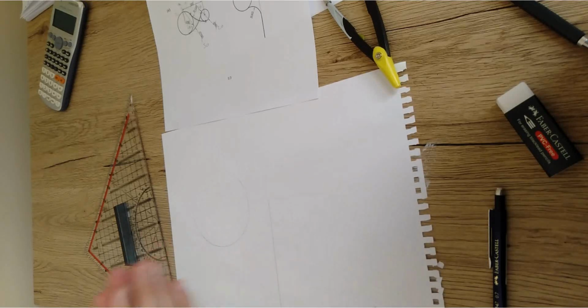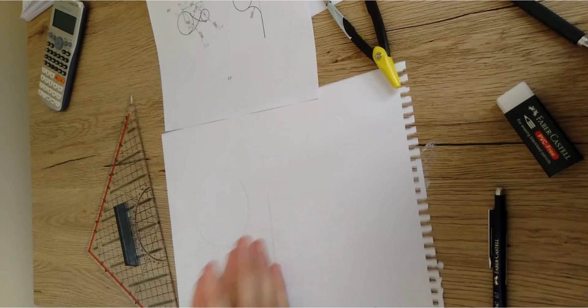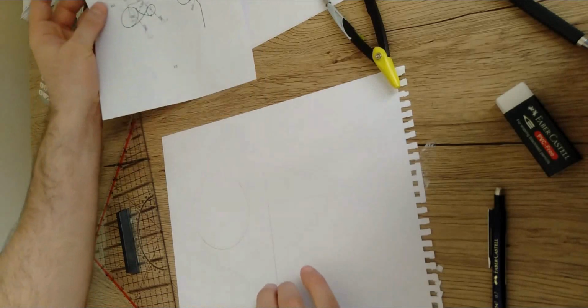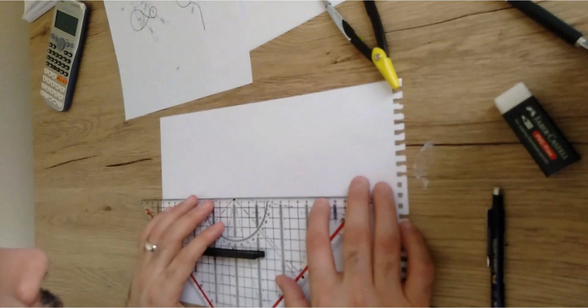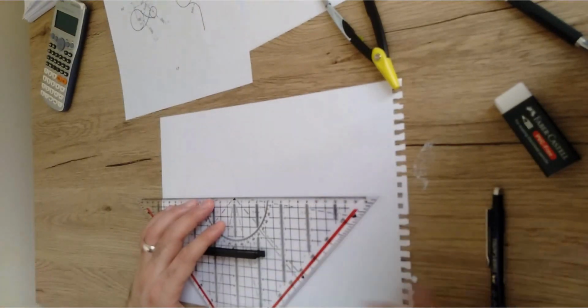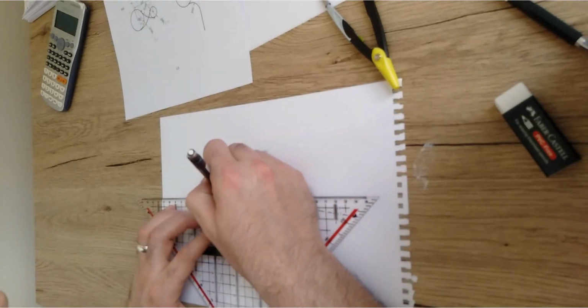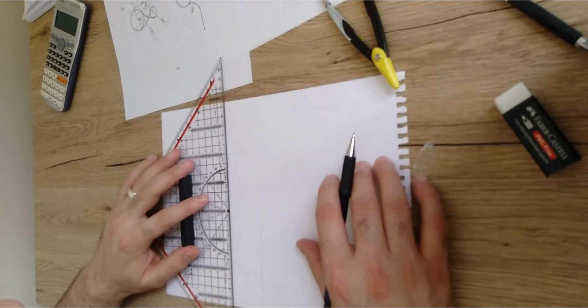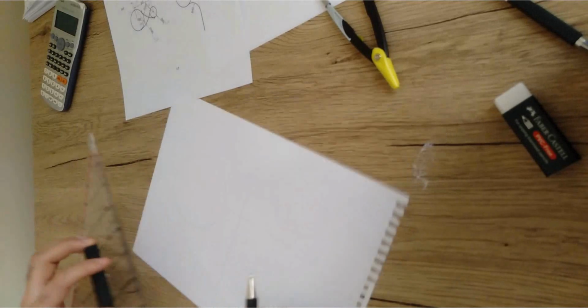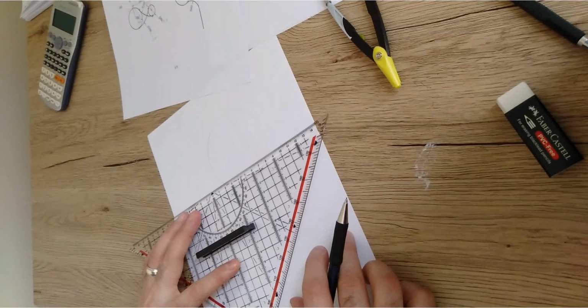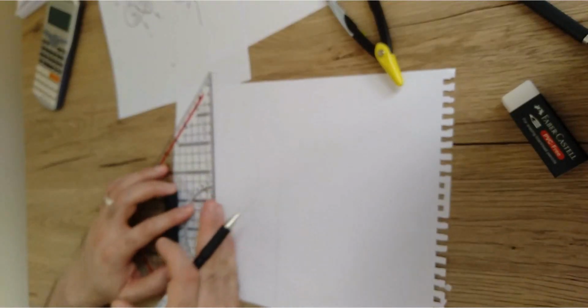For the line, I have to draw a line that is exactly parallel to this line, but with a normal distance between them of 40, which is exactly the same radius as this curve. So what I'm gonna do is measure over this horizontal line a 40 millimeter distance, and then mark a point. 40 millimeter is gonna be this point. Then I'm just gonna draw a line that is completely parallel to this vertical line, right? Even if you try to double check and give it rotation here, it should be completely parallel to this vertical line. So this is the first locus of the center point of the curve.